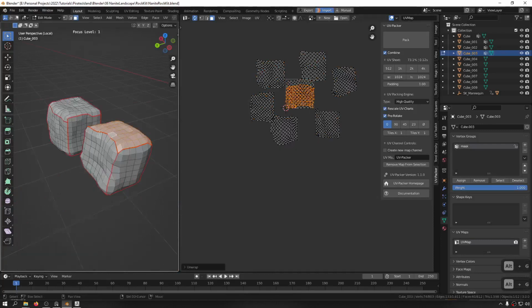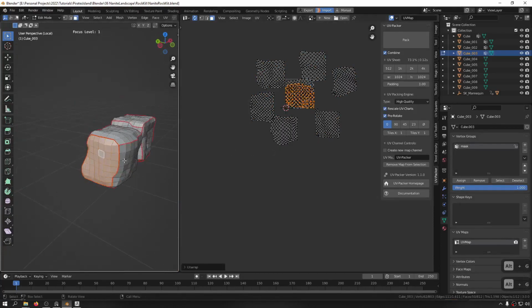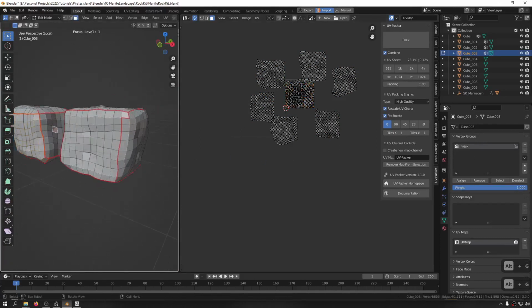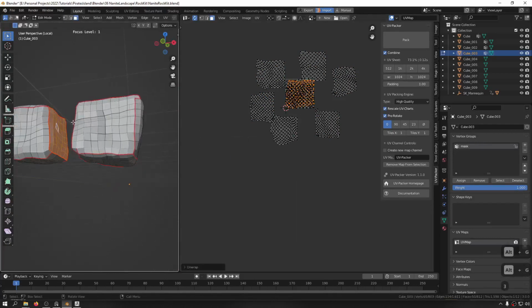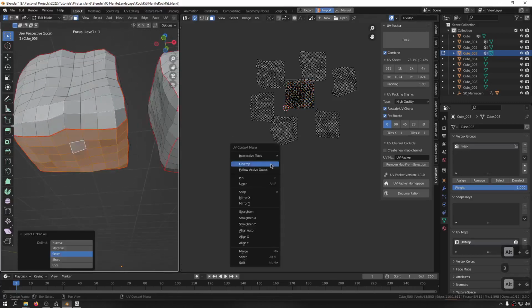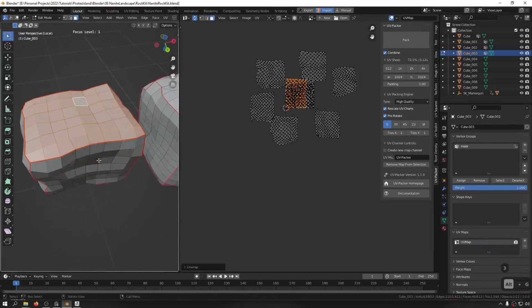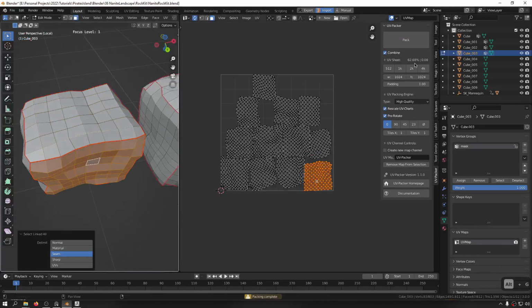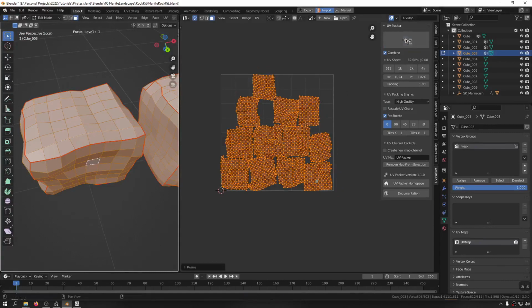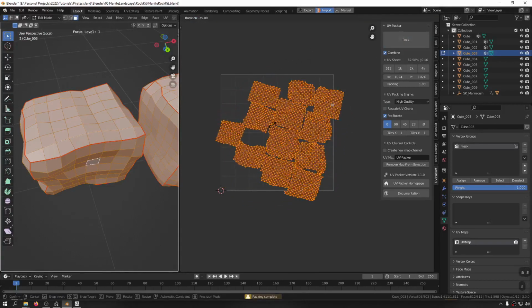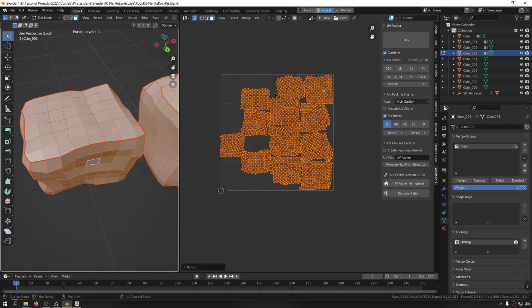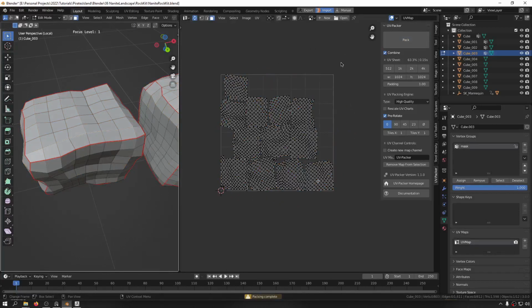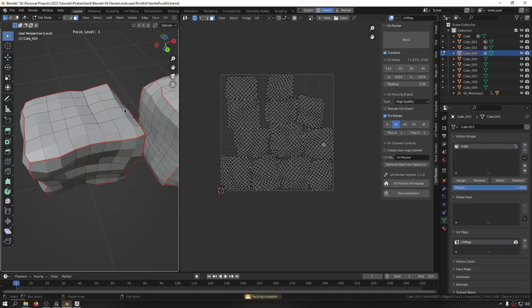and because the lines are there, you're getting a good unwrap. And this UV creation is a lot better compared to the previous generations. So unwrap again. Okay, let's hit pack. And now we're getting 62. Let's select them or do a rotation. I believe this way we're getting better. And yeah, this one we're getting 71.